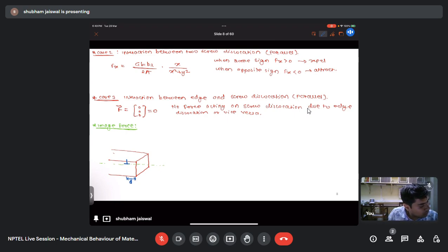So here I am putting one. Let's say this is d. This is my imaginary dislocation, and it has the same Burgers magnitude. Okay. So what will happen? This dislocation applies some force so that the dislocation inside the material comes out, and that is the same as the attractive force. Okay. And this force is only experienced by a dislocation near the surface, up to a few nanometers.